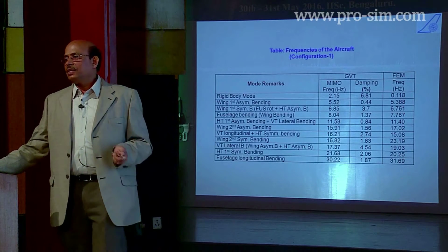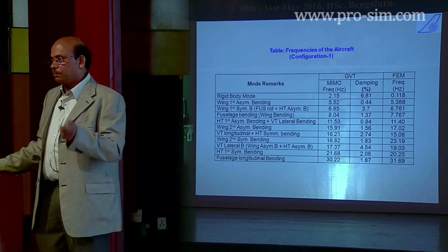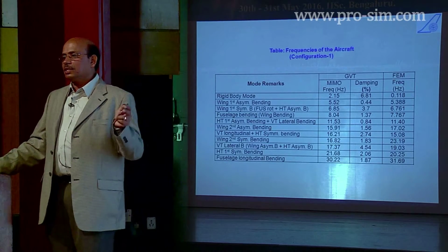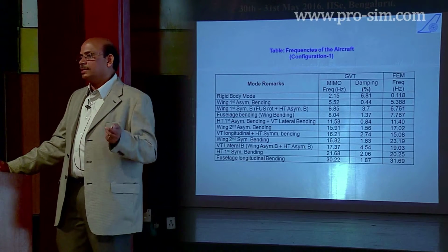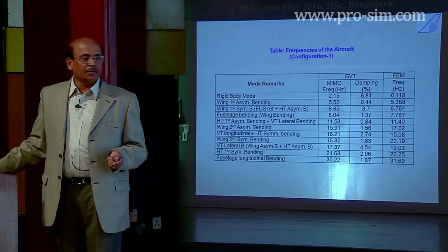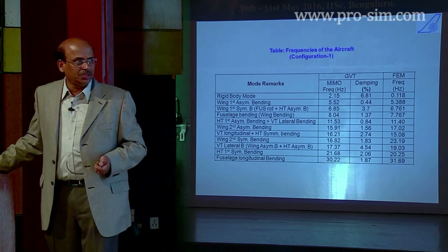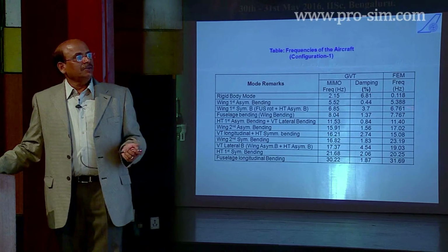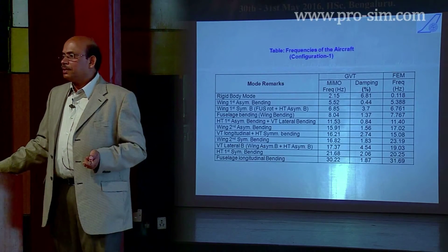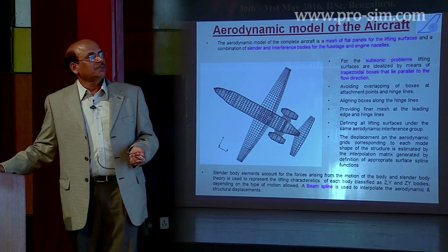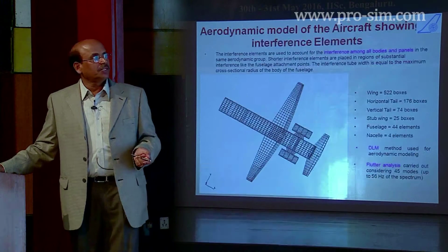Wherever tuning up was required, model updating was required, like what Professor Manohar was telling. Of course, here the problems are one way simple, because we are talking in terms of linear structures, but when it comes to nonlinear structures, problems get complicated. And when we talk about uncertainties, then all those Bayesian techniques will come into the picture. So once the finite element model was tuned up, we used it for doing our flutter analysis. This is the aerodynamic model that was used. Basically, a panel method has been used here.